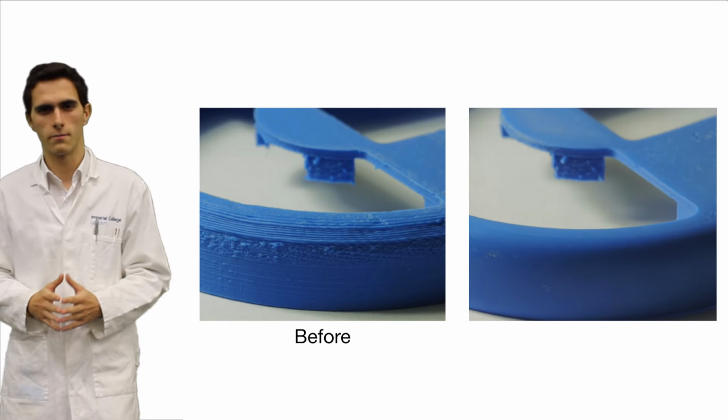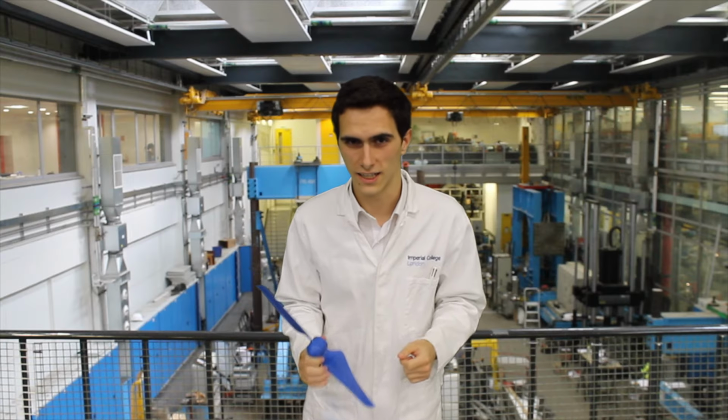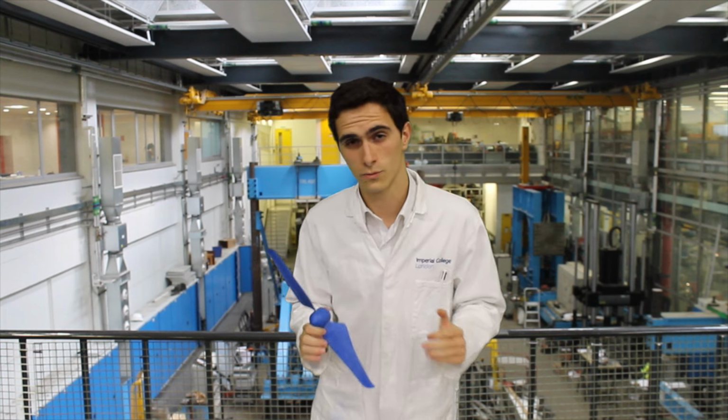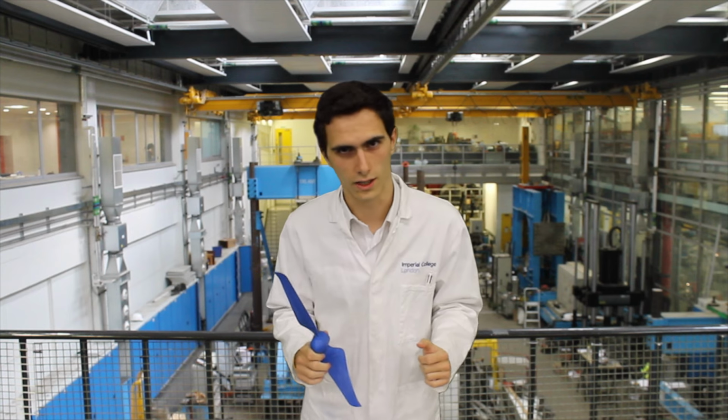Manufacturing also induces errors. To investigate these effects, with the help of Mr. Grant, a laser measurement analysis of our model was made and compared to the original CAD design. It was found that the twist angles differed by a maximum value of 1 degree, and that our chord distribution was close to the one expected. To limit these effects, bead blasting can be used to remove excess material, and vapor smoothing can be used for a better sanding. Rectifying the twisting of the blade and implementing these improvements would vastly improve the performance of the blade, which would lead to a wind turbine design that will revolutionize the energy industry through the supply of cheaper power.